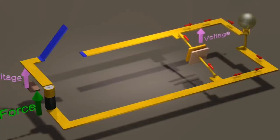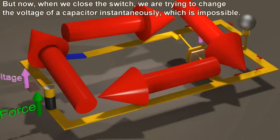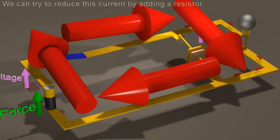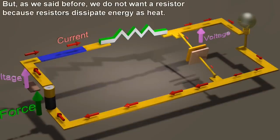But now, when we close the switch, we are trying to change the voltage of a capacitor instantaneously, which is impossible. As a result, an extremely large current will flow to charge the capacitor, and this can cause considerable damage. We can try to reduce this current by adding a resistor. But, as we said before, we do not want a resistor because resistors dissipate energy as heat.